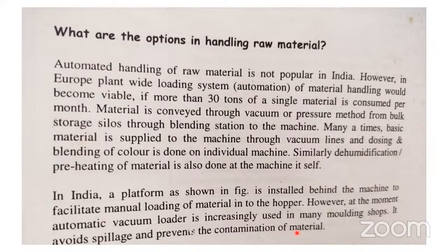There may be shrinkage, maybe some surface problems. There may be some voids present in the article. To remove that, and even by heating, your cycle time is decreased. By preheating, your cycle time is decreased. Therefore, there is always a benefit. But you have to do this operation immediately.